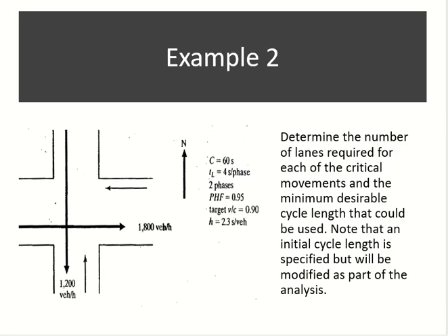Because nobody is coming from the other side. Okay, but if I had this and this both, it will not work. Two phases will not work. Somebody is coming from here, I need a phase for him, and somebody is coming from the other side as well, right? He may also want to take a left turn, so he may need a separate phase. Got it? He or she.